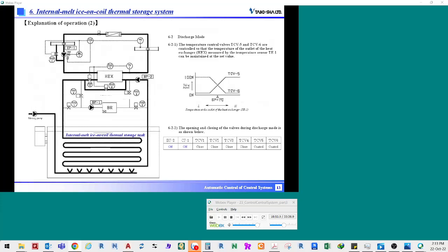As a result, calculate the heat generated by manufacturing equipment and consider factors including the electric capacity and the operating ratio of the device. The chiller is separated from the circuit. The chilled water pump determines the heat transfer load water to the load side. Determine the coefficient of overall heat transfer based on the characteristics and thicknesses of the material of the heat exchanger for chilled water, and determine the heat transfer load of the construction framework by using the result.